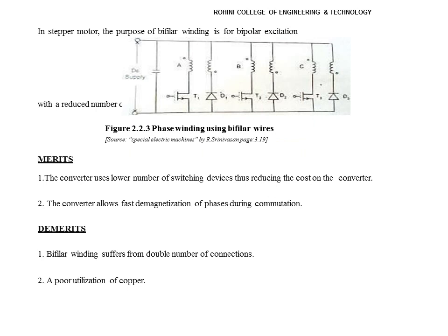Then, the phase winding using bifilar wires. Here, each phase winding consists of one semiconductor device, and one bifilar wire is magnetically coupled to the phase winding, and this bifilar winding is connected to the diode. Similarly for phase windings B and C. Each phase has two exactly similar windings, as shown in the figure. These bifilar wires used for each phase consist of two identical windings, magnetically coupled, and one of them is excited.